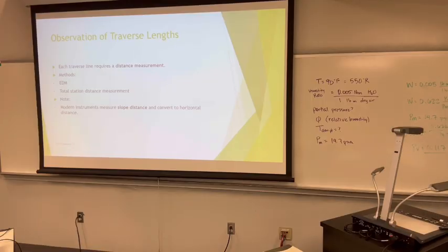We have done that where we measure our rounds every time we flop our scope, go to our face 2, take our indirect measurement. When we sight our backsight indirectly, shoot a distance again, turn to our foresight, shoot that distance again. And then when we go set up on our foresight and come back to that backsight where we just occupied, we get distances measured again. This all comes into play when we start doing adjustments and adjustment computations of traversing.